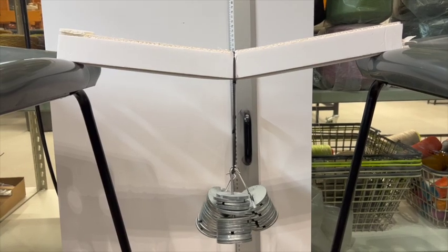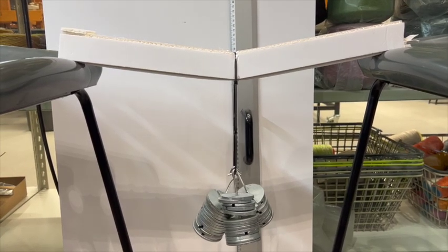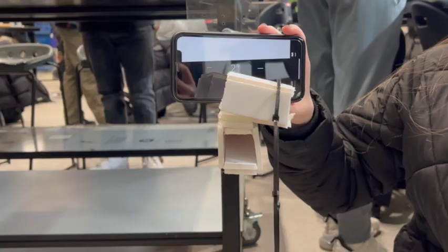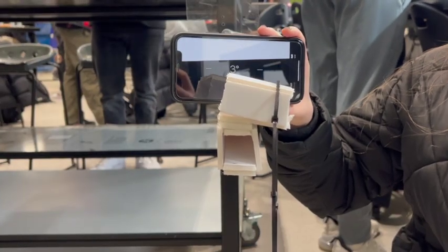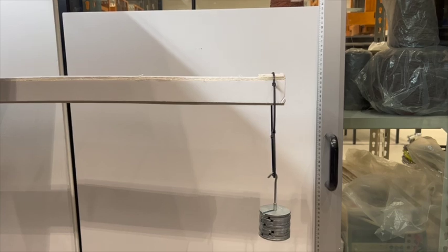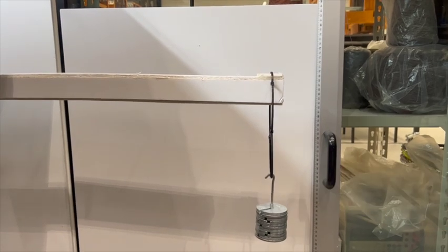In-person testing then confirmed that the rectangular beams fitted these specifications. The maximum torsional compliance had to be less than 3 degrees per Newton meter, and the maximum deflection had to be less than 15 mm.